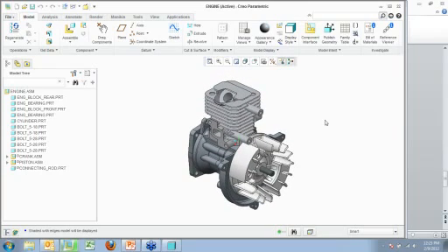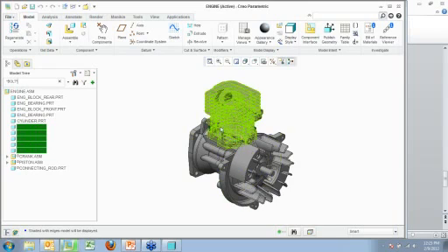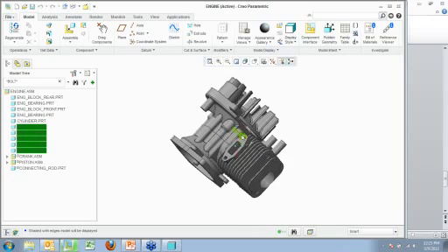So if I'm going to go in, and now I need to find some bolts. One of the things they've added in the model tree is a search bar, where I can go in. If I'm looking for bolts, obviously this is a small part. You can see all of my bolts right there. But let's say this had 100,000 components, then I go in and type star bolt star, hit enter, and it'll find all of the parts that have bolt in the part name. So you can see my 5 by 18 millimeter bolt, my 5 by 28 millimeter bolt are all highlighted. In the model, it also highlights them in green.